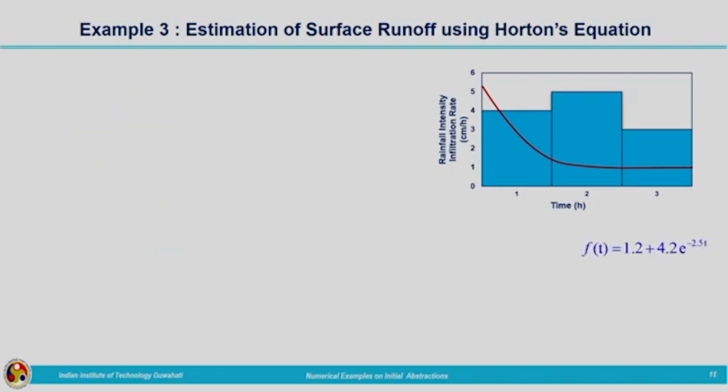So, now you can see up to a certain point, that point corresponds to the meeting point of the infiltration curve and the rainfall hydrograph. When we were discussing potential infiltration and actual infiltration, we have seen that if F value is greater than the intensity of rainfall, all the water which is falling as rainfall will be infiltrated into the ground, right. So, here you can look at the infiltration curve and the rainfall hydrograph.